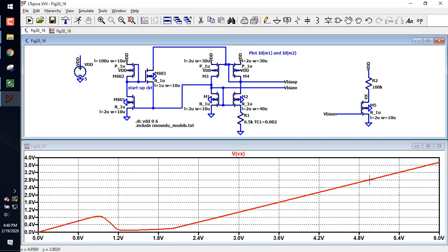So does everybody see what I'm doing here? You see how I'm changing VDD and it's keeping the current constant? That's why in my monitor I drew a 75 ohm load to ground, because if VDD changes, how does that change the voltage across the resistor? It doesn't. You don't believe me? I don't blame you. Let's prove it.